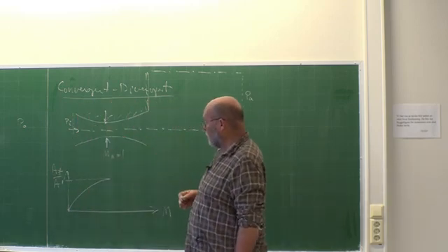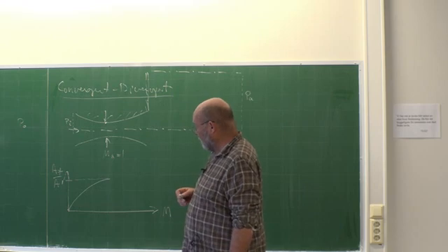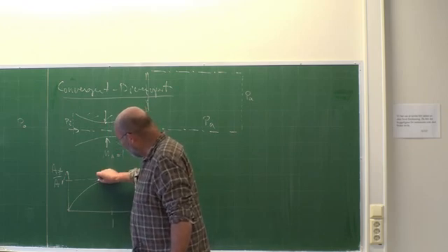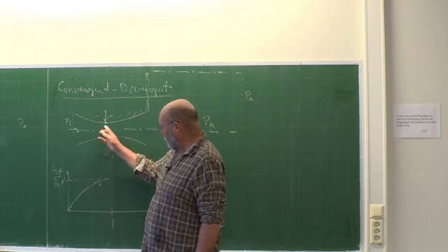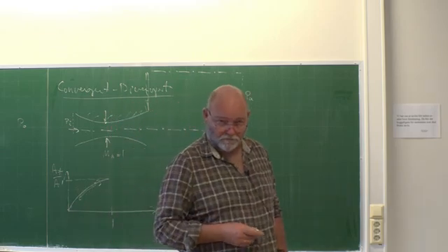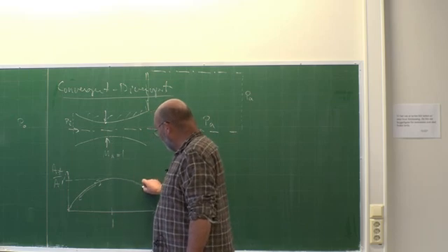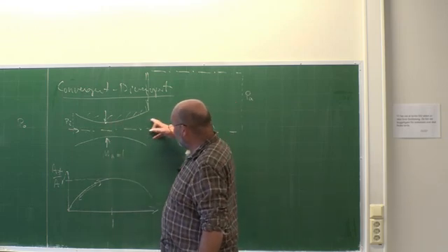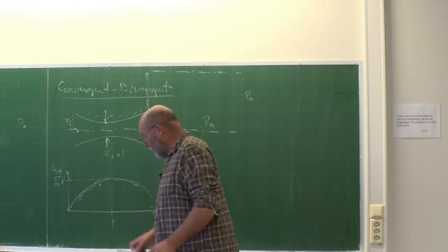If the driving force is strong enough, then we can have a choked nozzle. If it's not, then it's going to stop here somewhere. So then it can go up here. Velocity is increasing. But then on the other side, the velocity is going to decrease. It goes back again. But if the driving force is strong enough, then you will actually have something like this. Then the velocity will actually increase on the other side. It will go here. So there we have Mach 1.